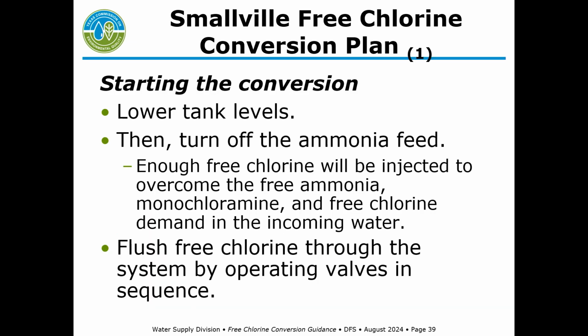Starting the conversion, you're going to lower the tank levels and turn off the ammonia feed. You may have to increase your free chlorine injection rate to overcome anything that's coming in the incoming water, and then flush free chlorine through the system, in sequence as we already discussed.